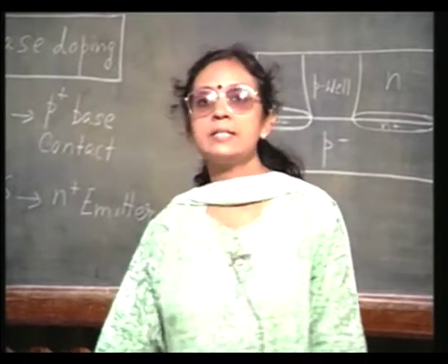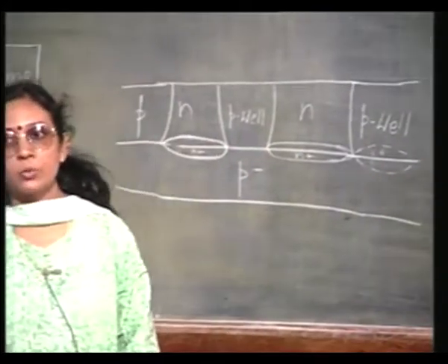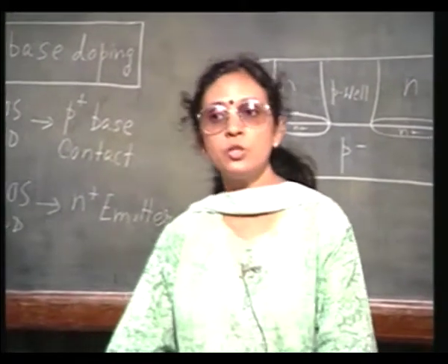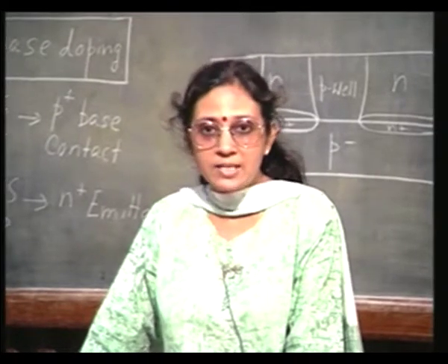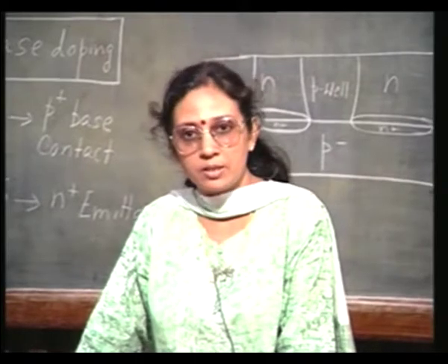So, we added the buried layer and the epitaxy, that is the retrograde well structure. Okay. So, basically we killed two birds with one stone. We prevented the latch up problem for the CMOS as well as we reduced the collector resistance problem of the NPN transistor.